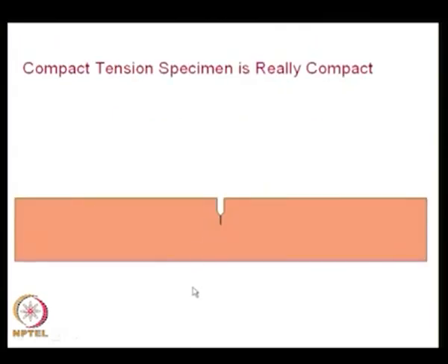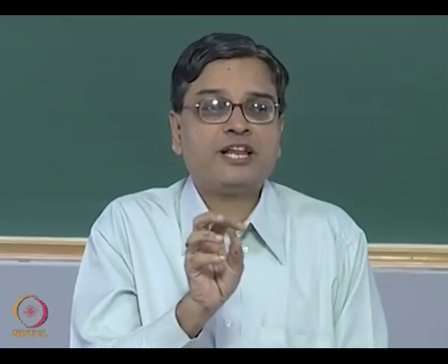And I had also mentioned in the case of nuclear installations, even though you have the containment made of very high tough materials, because of neutron bombardment over a period of time the material degrades, it becomes brittle. So, one of the techniques that people employ is they stack several specimens in the reactor and take the specimen periodically out and test it to find out the material toughness, how it has degraded as a function of life of the reactor. So, you need to stack as many specimens as possible in a given area.